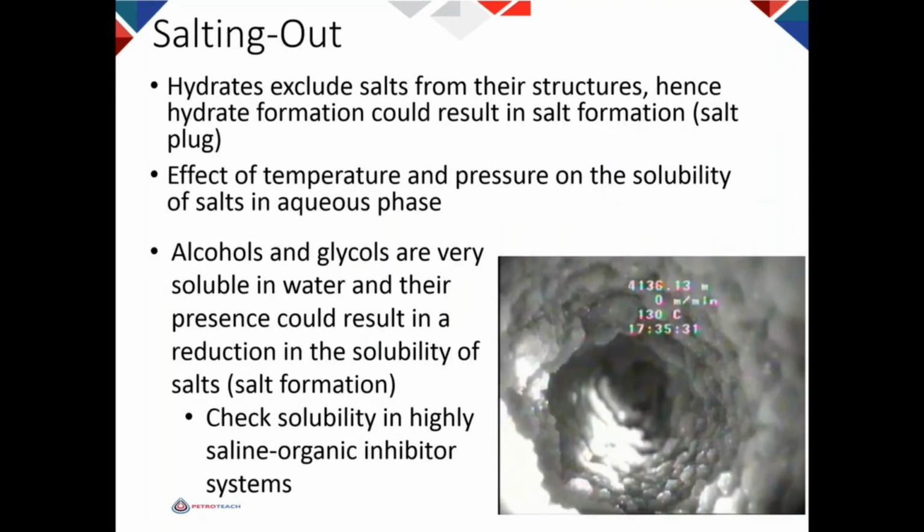When you are using thermodynamic inhibitor, you need to be very careful about not forming a salt block, because salt is soluble in water but has a limit for solubility. For example, NaCl, you can dissolve 25% in water, but any more than that, it cannot dissolve. But the alcohols are miscible.